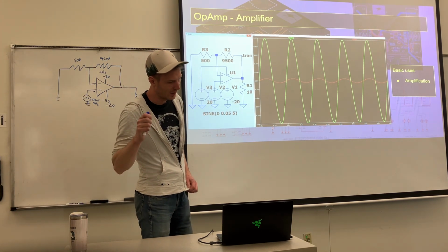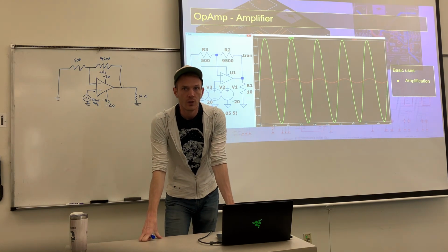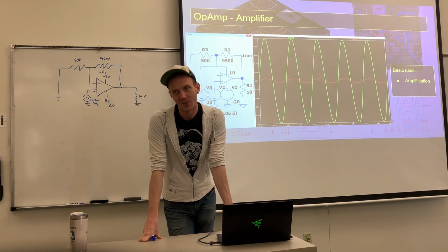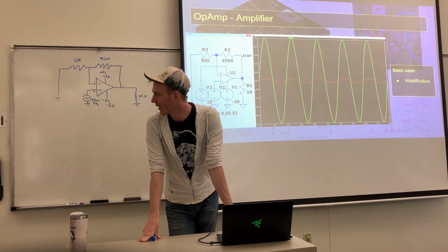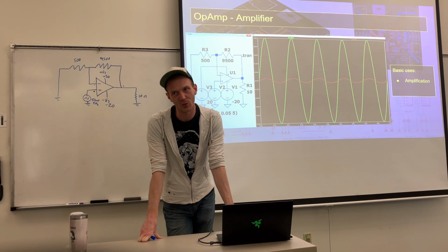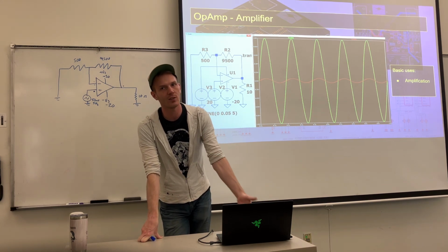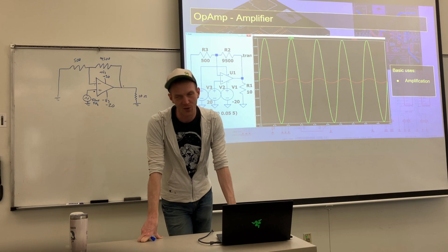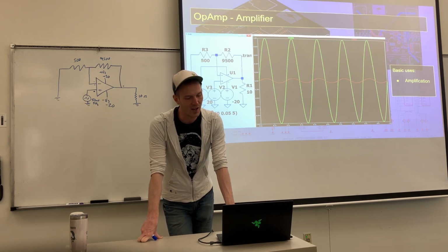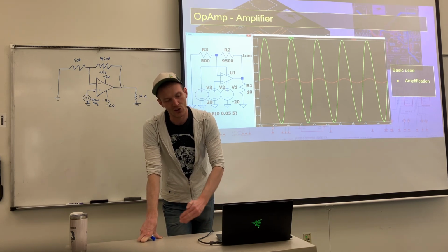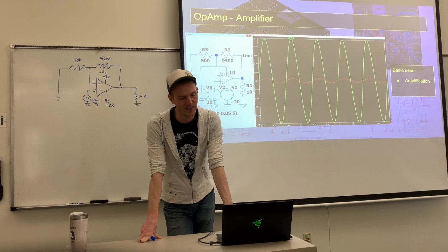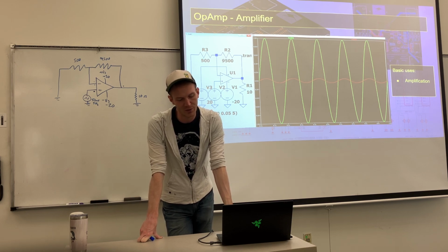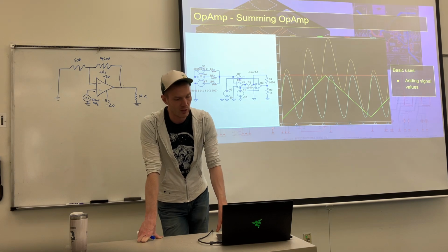Does everybody get that before we move on? This is a very convenient way to do amplification. Everything else we had earlier was a lot more about trying to figure out signals, and you would have to change your capacitors and inductors every time, and a bunch of careful stuff around transistors where you have to worry about a lot. And this is honestly pretty low sweat. You can just say, I don't care how fast it's coming in. I don't really care how big it is, as long as it doesn't exceed my supply voltages. The only parameters you really care about are output current and the maximum you can supply to it. So next we're going to move on to a summing op-amp.